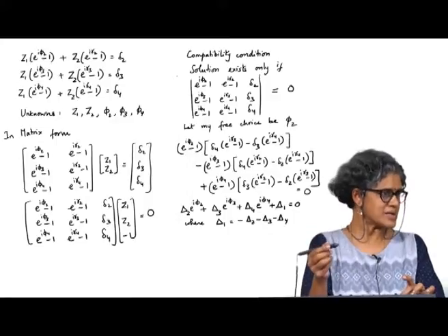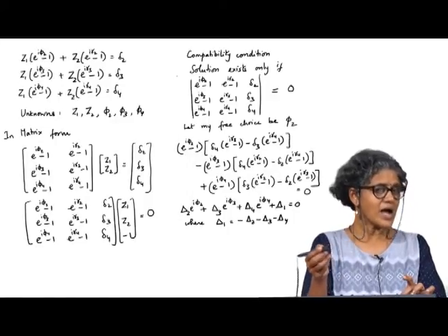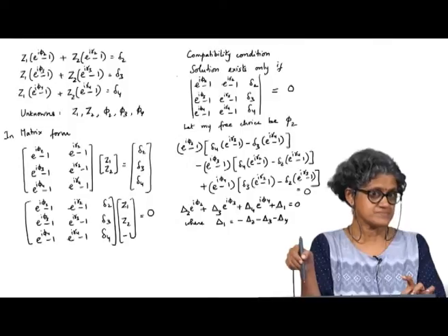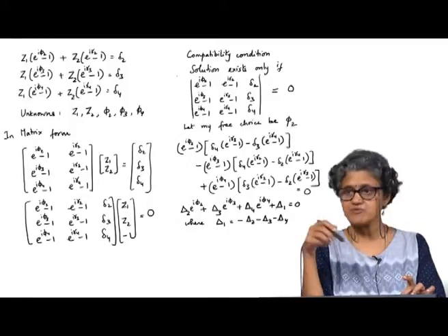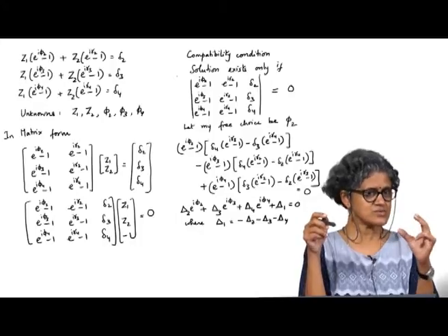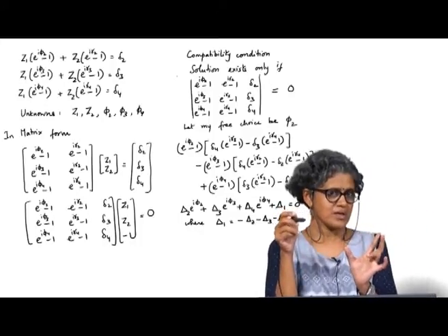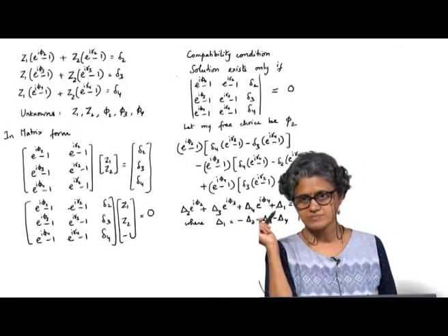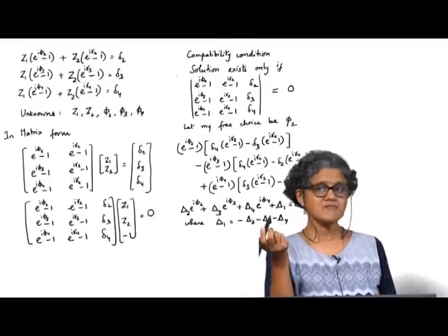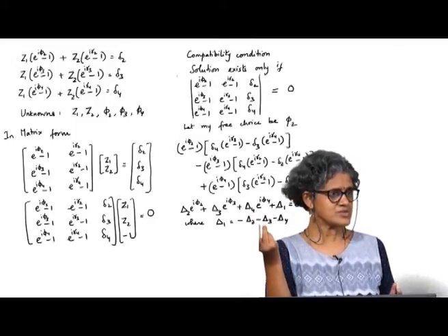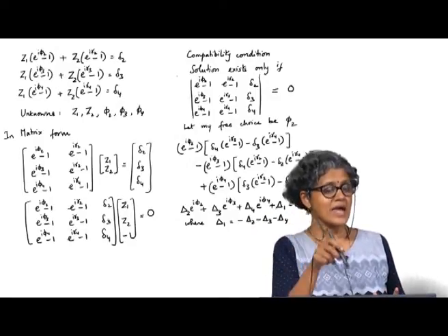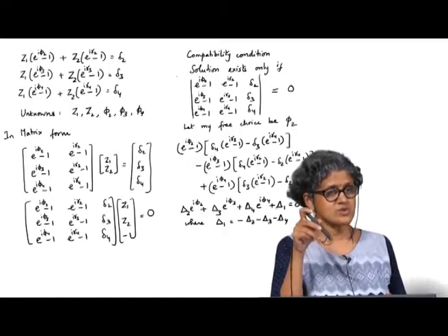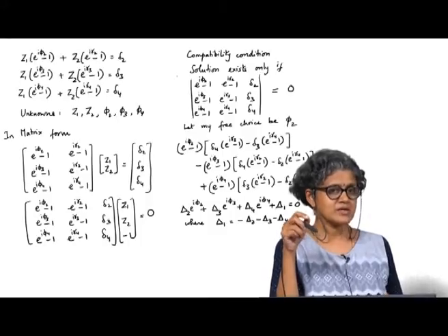Now, I can't choose arbitrary phi 2 and phi 3. I can choose phi 2 and phi 3 such that it satisfies that compatibility condition, which means essentially solving for that 4 bar. So, specific combinations will give me solutions for this. Phi 2, how many choices do I have? I have an infinity of choices. So, again I can technically solve the 4 position problem. I do have an infinity of choices. So, I should have an infinity of solutions.